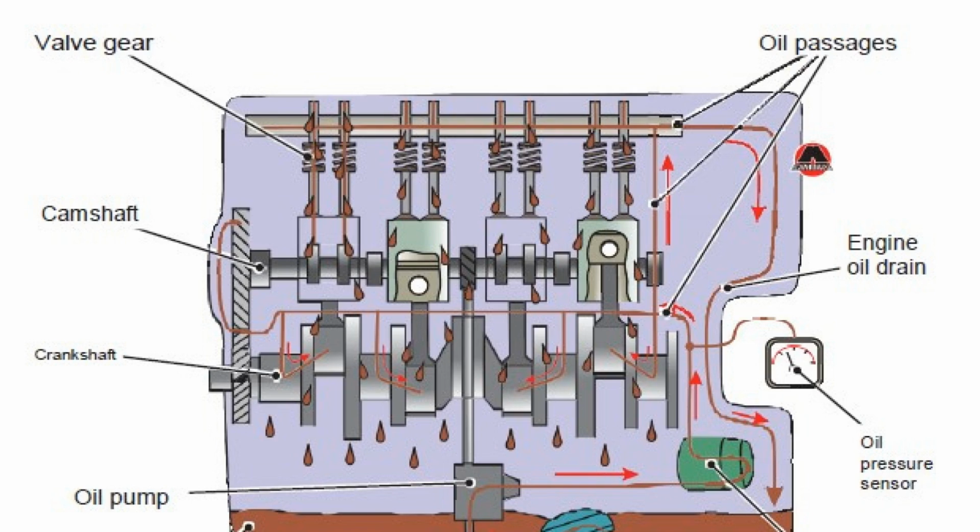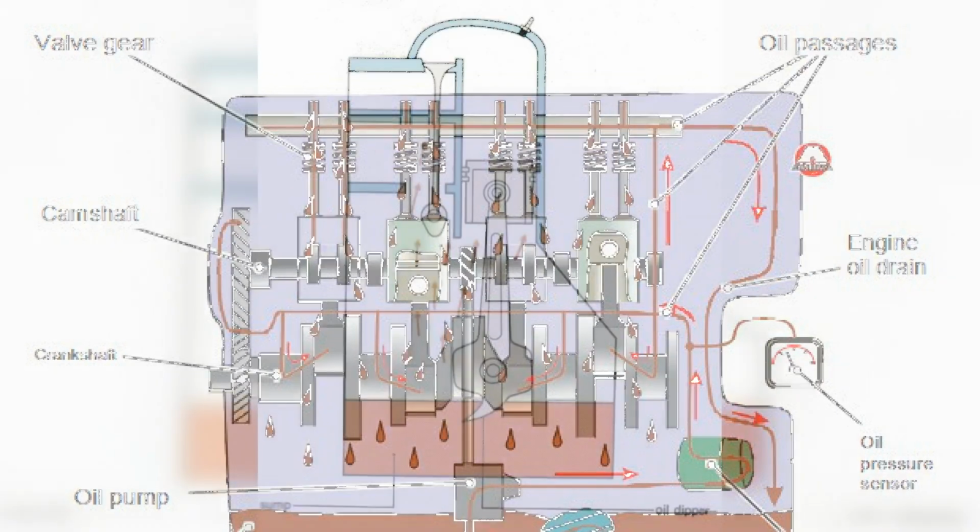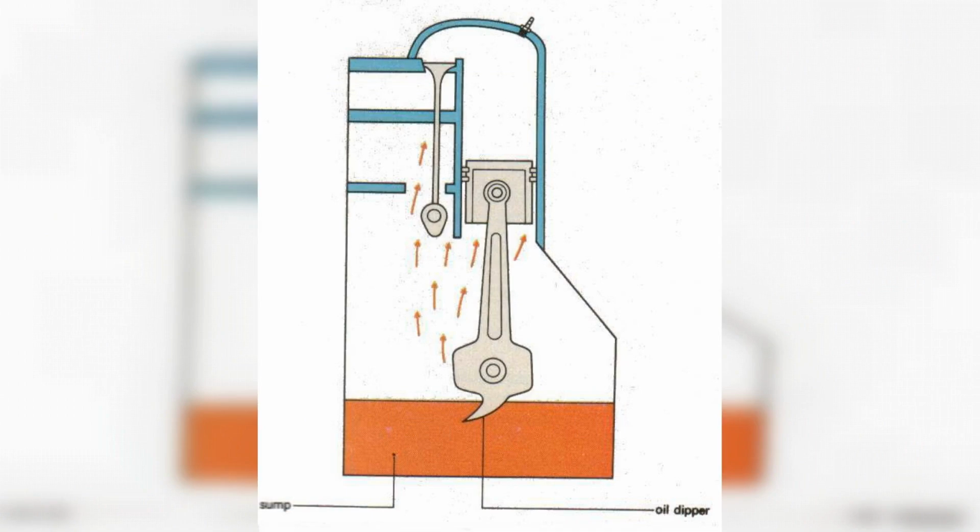Excess grease is squeezed out through the technological gaps, and, falling on the rotating parts of the crankshaft, splashes throughout the volume of the engine, lubricating piston pins, internal surfaces of cylinders, other parts of the engine. In parallel, oil is fed through the oil line to the camshaft, lubricating its bearings, gears and axles of valve rocker arms. A small part of the lubricant, no more than 20% of the total volume circulating in the system, gets into the fine filter, from where, having been cleaned, it goes back to the oil pan.